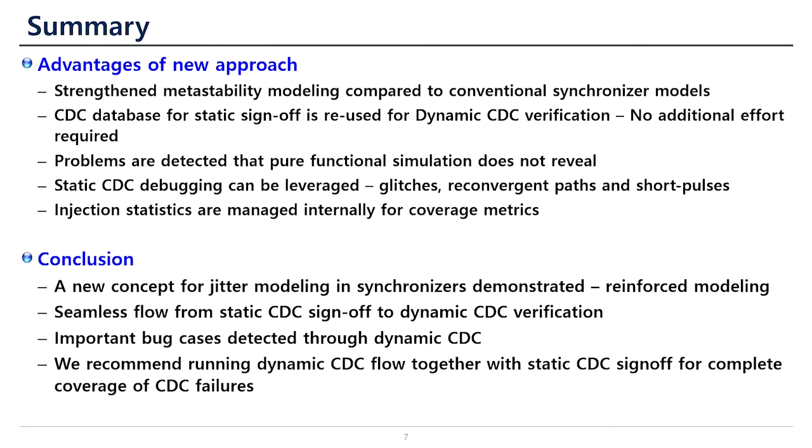Another point is that to achieve this goal, we can reuse our previously prepared CDC sign-off flow. On top of that information, we can extract some models and add that information during simulation. With verification based on simulation, we can reveal many kinds of problems that are hard to detect during normal simulation.